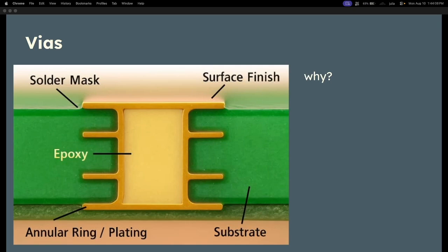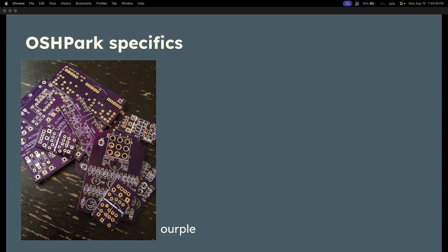You're not going to need them too much for the circuit we'll be making today, but for the circuit tomorrow, you will be designing your own circuits and they might get more complex from there. So I'd say you might need these, because they'll help connect your ground planes together. So pretty important. And they can even connect from the surface to inner layers, which, if you're getting into more complex PCBs that use more than 2 layers, is going to be very important. But we're not doing that for this workshop, but maybe in a future class.